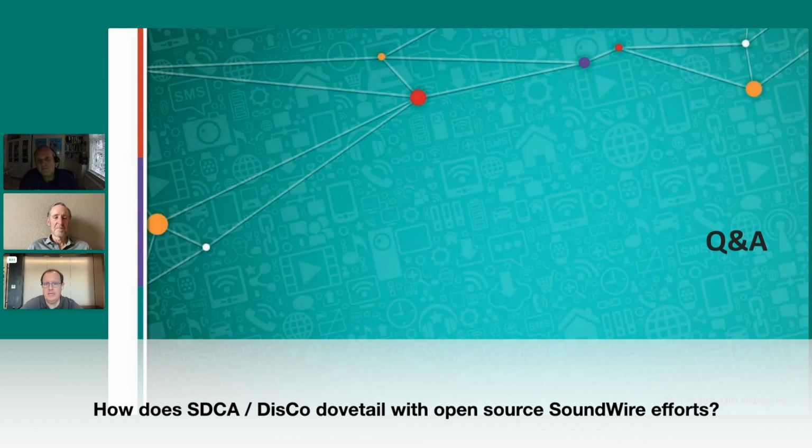The Linux SoundWire driver, at least on an Intel system, interacts with the DisCo data to determine the hardware capabilities. Similarly, the Linux SDCA drivers interact with DisCo data to learn about the SDCA functions that they might want to work with.